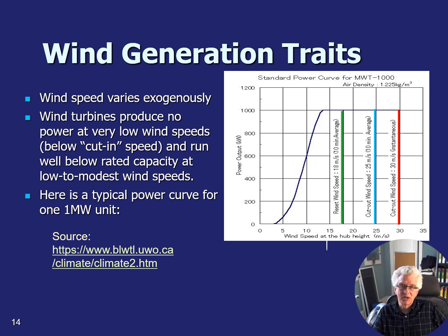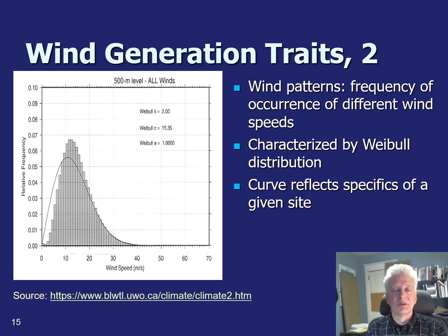Again, AHO does a great job explaining all these kinds of things, and they talk about some really neat control technologies on the margins that I can't really do any better than they did. Now let's look at the statistical properties of wind. Whatever location you work in, you can set up a wind measurement instrument, an anemometer, and let it run for a good length of time. Often the studies will take 1 or 2 years of data.